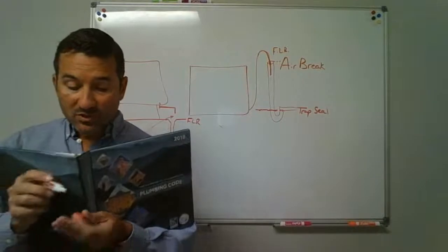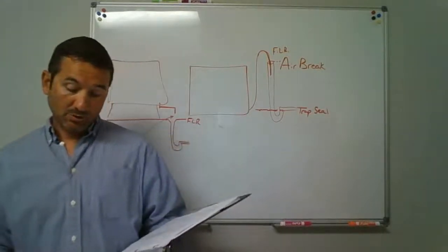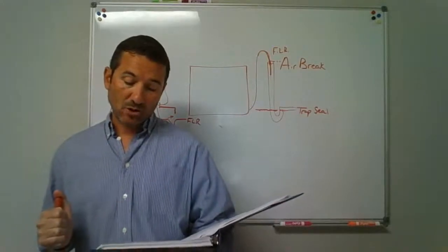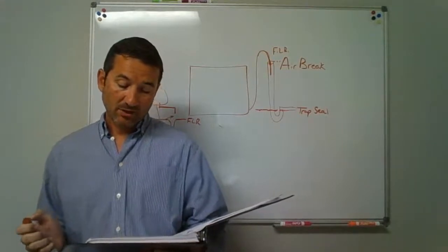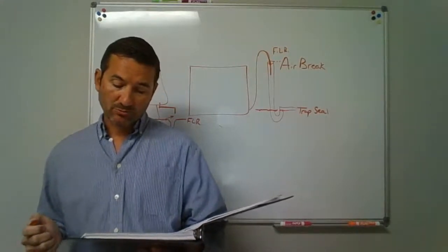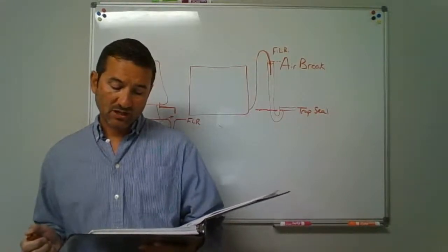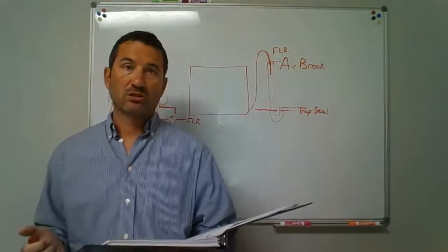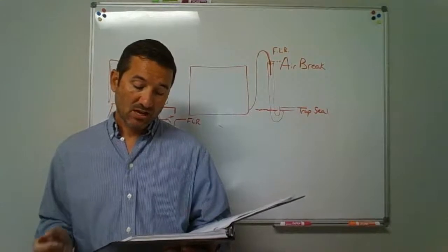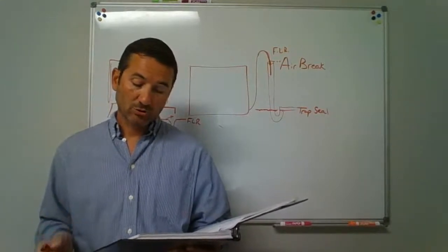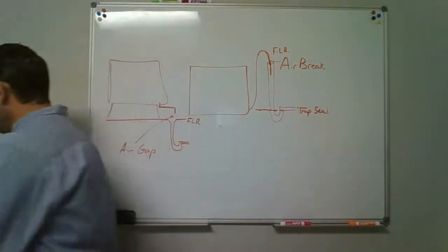An indirect waste receptor, as defined in Chapter 2 on page 9, is a plumbing fixture designed to collect and dispose of the liquid waste from other plumbing fixtures, plumbing equipment, or appliances that are required to discharge to the drainage system through an air gap. The following types of fixtures fall within the classification of indirect waste receptors: floor sinks, mop receptors, service sinks, and standpipe drains with integral traps. Okay, those are different types of the receptors on those.